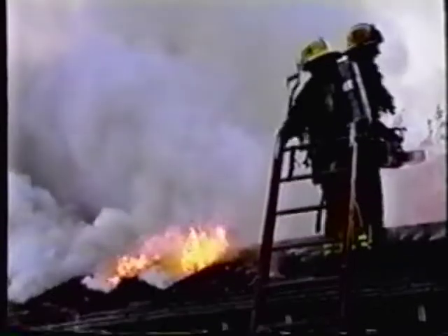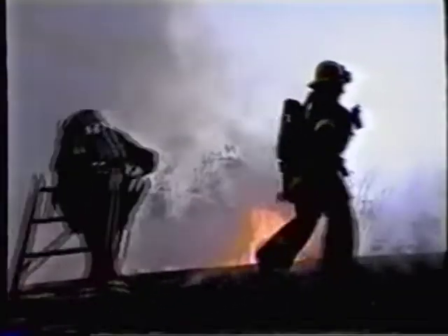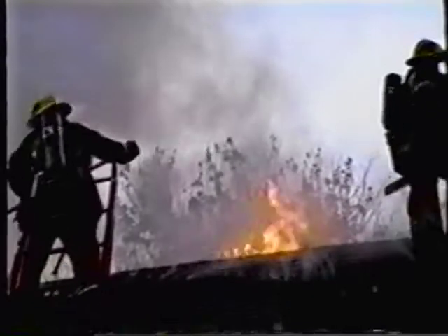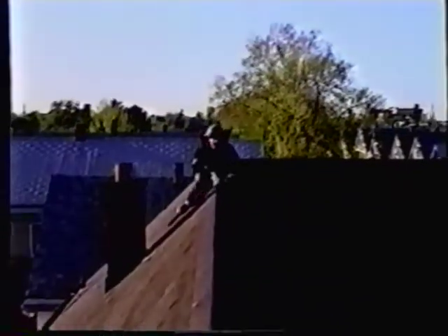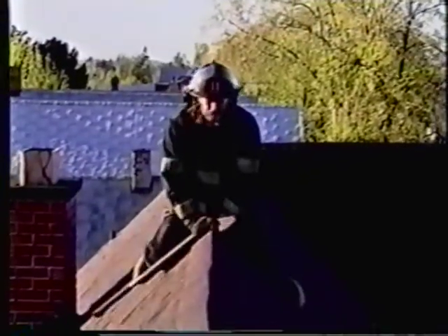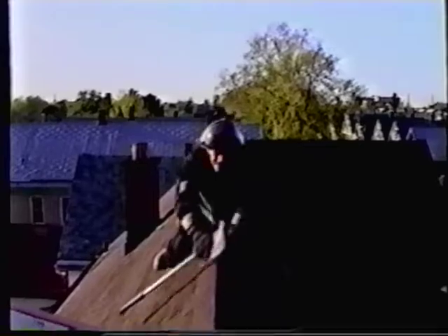If the only safe access to the roof is from the ridge area by portable ladder, members must be able to move safely across the ridge surface to the area where they will operate. On low-pitched roofs, 4 on 12 and under, walking upright is the easiest and safest way to move. On steeper roofs, it is best to straddle the ridge area in a sitting manner and inch your way across the roof. By staying low, the firefighter is less likely to lose his balance.